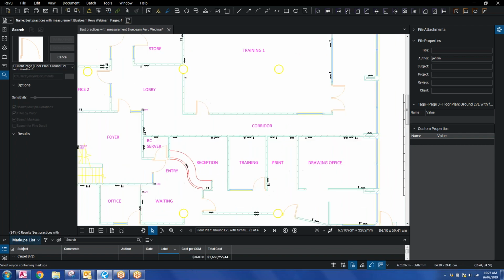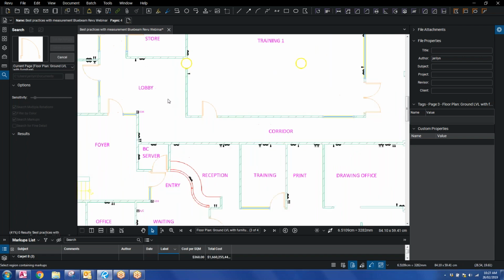Okay, so as we are waiting, I hope this session has been very useful for you guys, and we have learned something new from it. Basically, what I need to show you is that you always need to calibrate your drawing, make sure that the scale is right before you do any measurement. Once you start doing measurements and you realize that your scale is wrong, do not worry. You can always recalibrate it and recalculate all your measurements again.